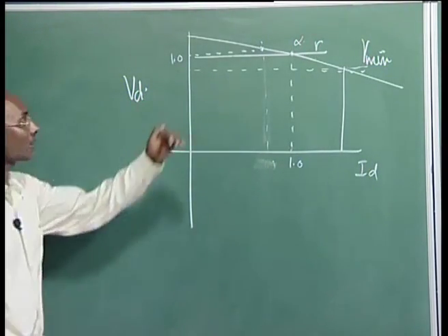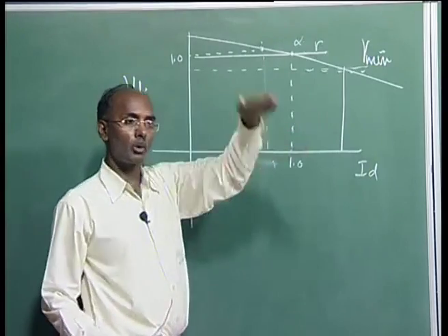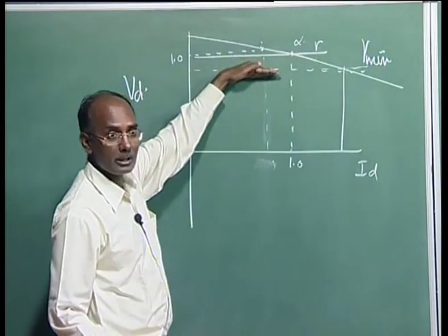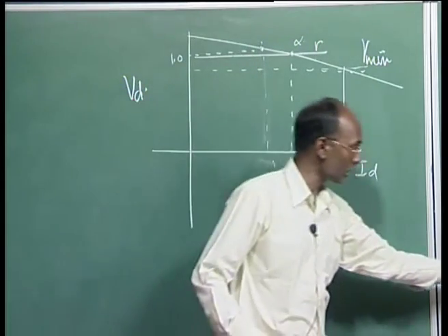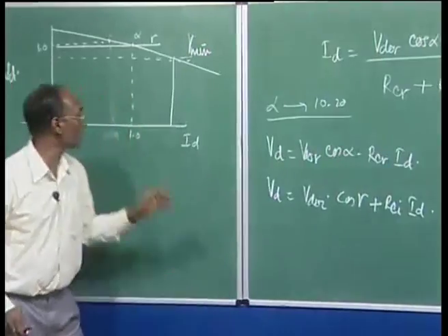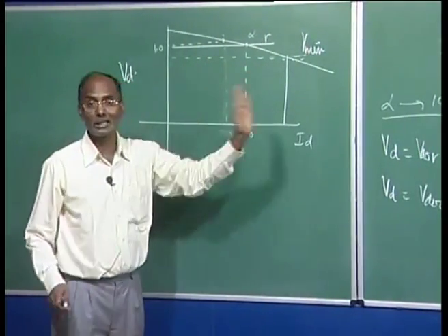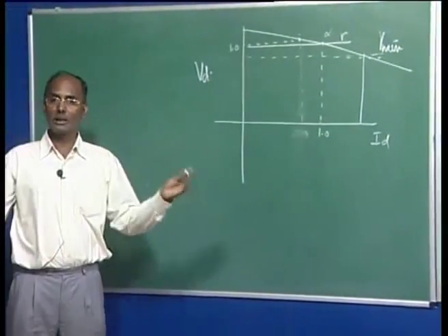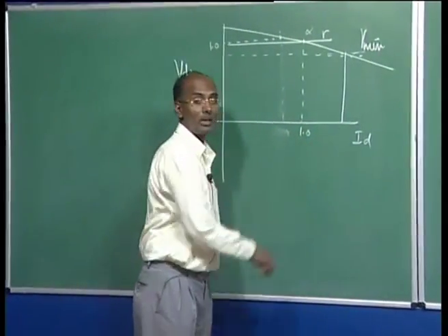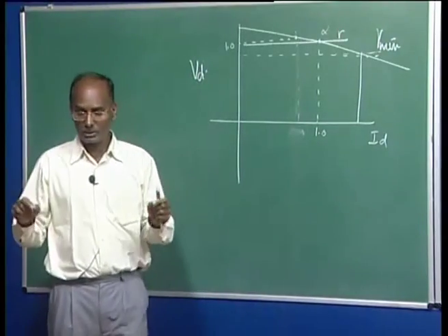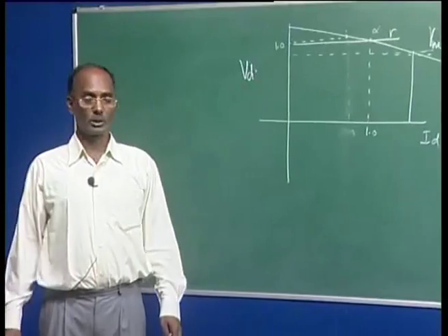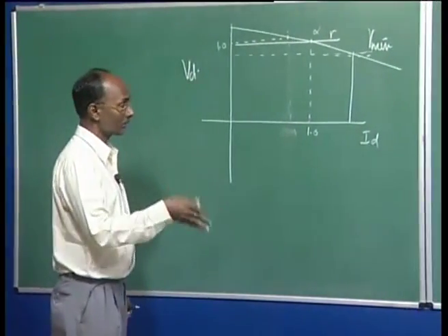If you are not doing anything in the rectifier, and the inverter end voltage has gone down, what will happen? This will have another characteristic because this value is changed. This is already minimum, we are operating. Other values are constant. Your ID will be here, which is increased tremendously. And once ID is increasing, that we should not allow, because this may damage your line, and also it may damage your converter valves, because more current will be flowing, more loss, and it may puncture your rectifier converters, thyristors.